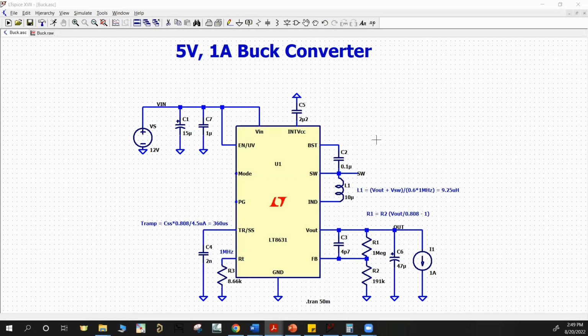So anytime you use an N-channel high side switch, you must use a bootstrap capacitor to give you that extra potential on the gate that enables the gate voltage to be higher than the source voltage. And then here we have the switch node, as we discussed in the typical buck converter. We have that switch node, which connects directly to the inductor.